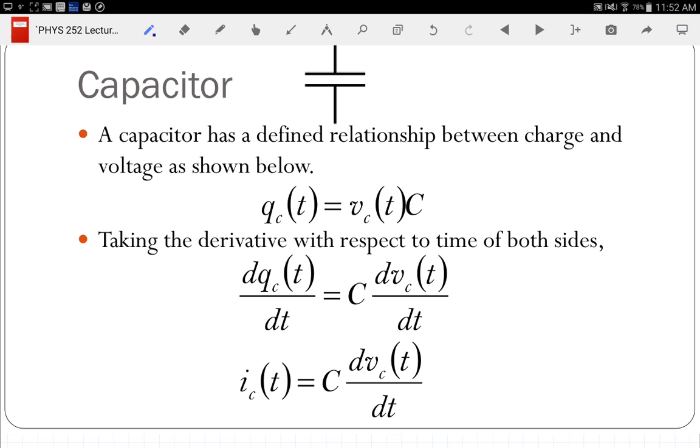I would think so too. This current is technically the current coming to the capacitor or leaving the capacitor, not the current between the plates. The current between the plates is going to remain zero. But you have, on the bottom you have charge going this way into it, on the top you have charge going this way out of it. The current is the same on both sides of the capacitor. And the capacitor is storing not charge, but storing a charge separation.